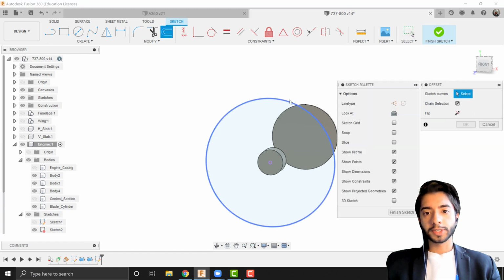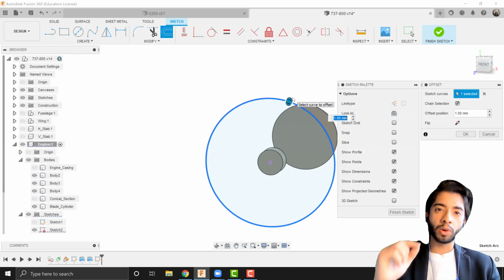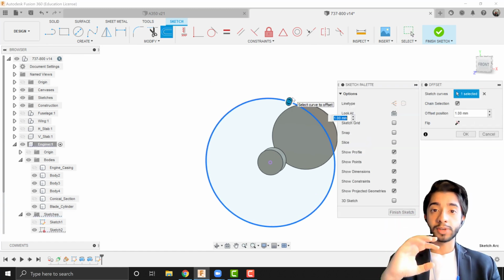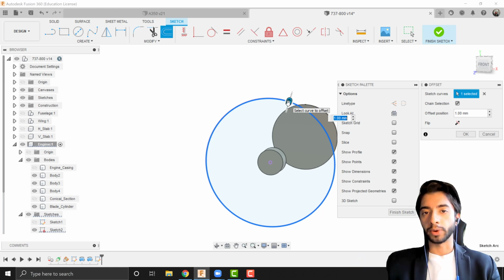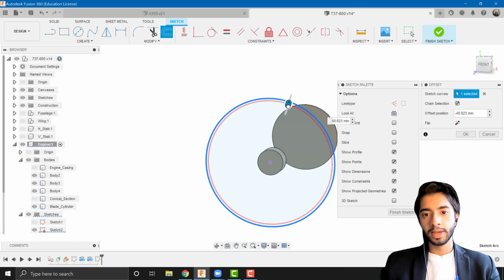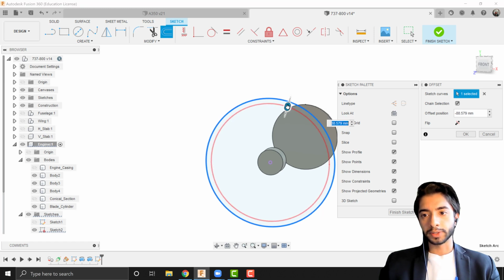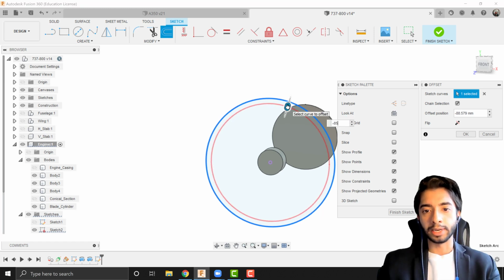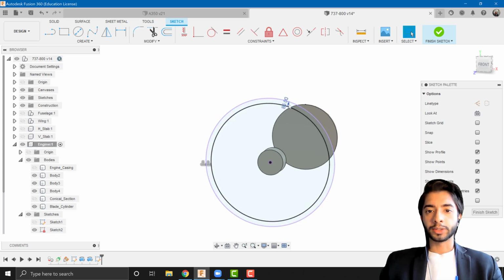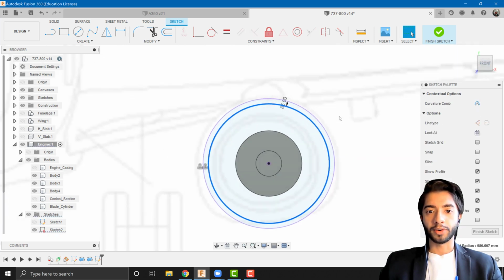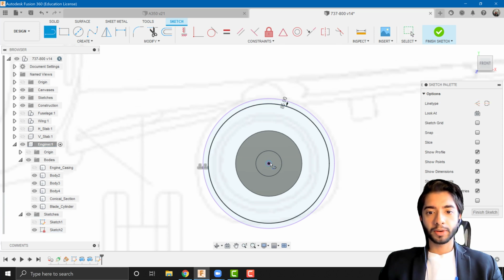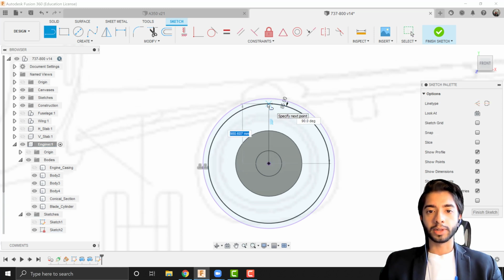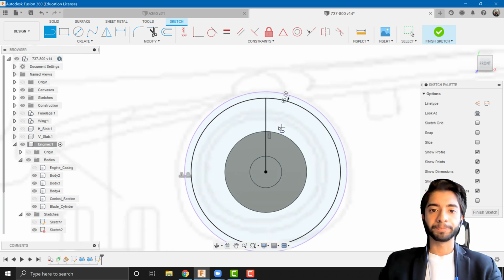So now we can offset this, because if we make the blade all the way up till there, then chances are it's going to start protruding outside the casing. We don't want that. We want everything to be inside the casing. So I'm just going to create a little bit of an offset here. Maybe I'm going to go with -85, and that will be our maximum height of the blade. Okay, so let's create a line from the midpoint and vertically upwards until that offset line that we've just created, so that black one there.